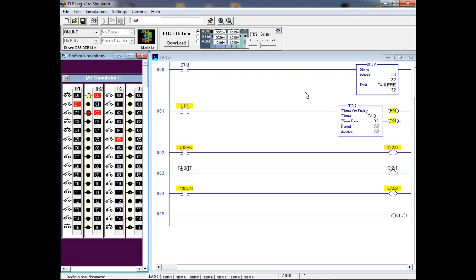So what registers do you think we have access to on counters? So what are our two types of timers? So what's the difference between a retentive timer and a non-retentive? Yeah, so notice anytime right here, so I'm gonna come up here and disable it, and what's the first thing that happens on this guy right here? It resets, right? Y'all understand that? Yes or no? Yeah, this is a non-retentive timer.